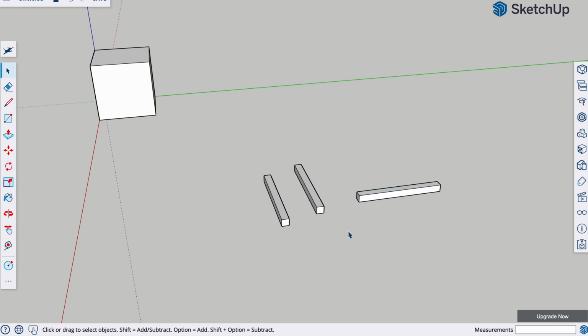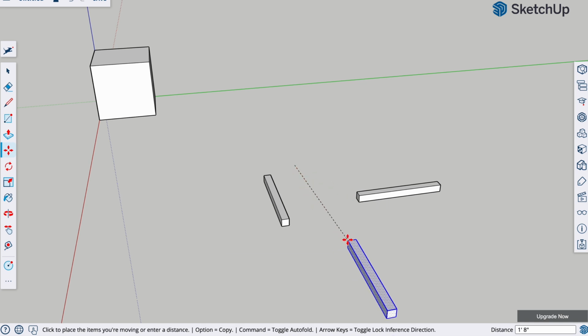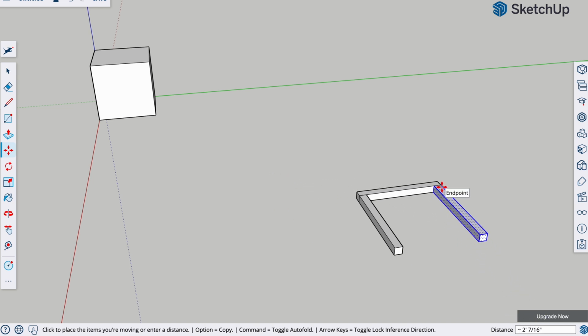And then what you can do is triple click the other 80/20 piece, hit the letter M, click one of the corners. So let's click the back right because we want this back right corner to go right here. Click that, the M, and then you can drag and it'll snap to a corner that makes sense. So if you're trying to move this piece from here to here, you don't want to click this corner because that's not going to snap to anything. But if you click this top corner, you can just snap to it right there. And then to click out, hit the space bar, click away, grab the other piece, grab that back right corner, drag it here. Perfect.